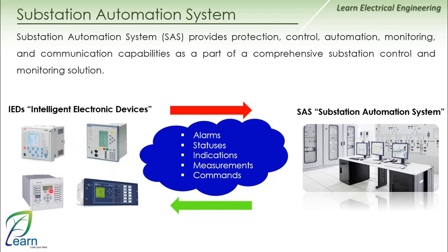But now all these relays are distributed, each one is separate. So, what's the solution now? The solution is quite simple. I will bring a set of panels, and these panels will contain switches. I will start connecting fiber cables between my IEDs and these switches. Of course, it's not these panels themselves that I'm pointing to, but panels that contain a set of switches like the ones you see, such as RuggedCom switches and others.